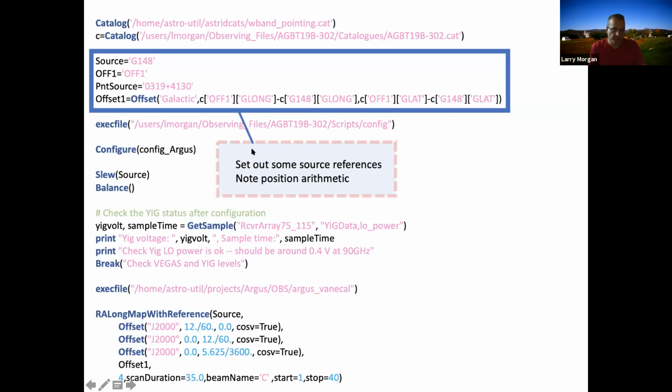And if you want to check something like that, what's nice is that if you have a print command in your script, when you validate your script, those print commands will be run. So you can actually check things like your arithmetic and so on, just to make sure your coding is correct, without the need for a simulator or anything like that.